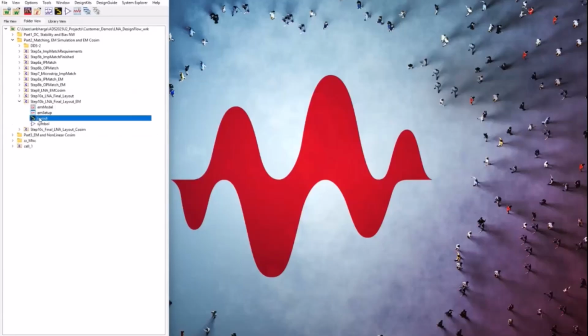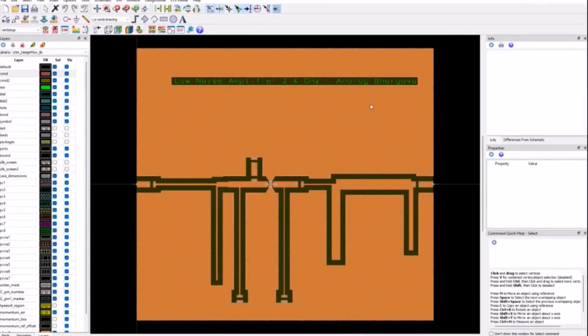So in the previous section, we did input side EM, output side EM separately. But then we can do a final layout, because that's how my PCB will look like. And I will do a full electromagnetic simulation of this entire layout. Reason I didn't do it from the very beginning, because I just want to make sure that you have the right confidence in the result before I go and do this complete layout. Because when you do a big layout EM simulation, it takes some time. So I divided the problem into left half, right half, attained the confidence when everything is working okay. Then I went ahead and created this entire layout.